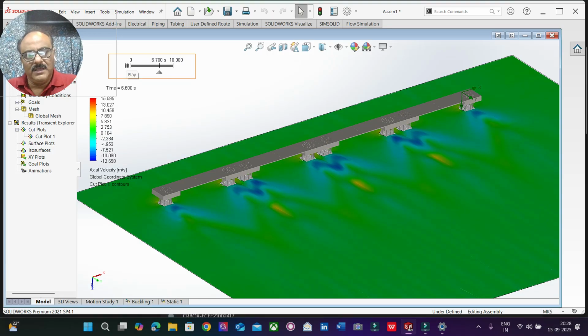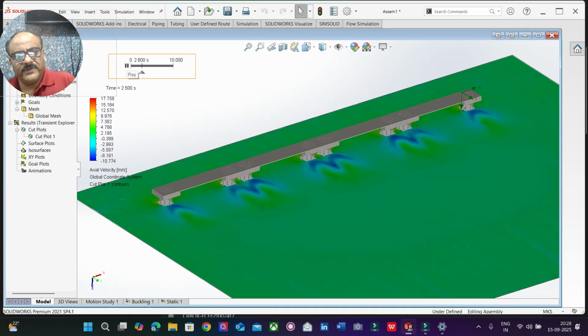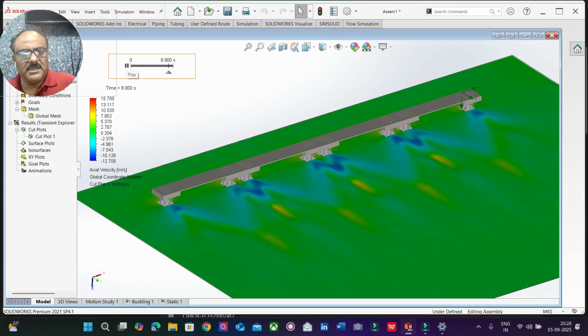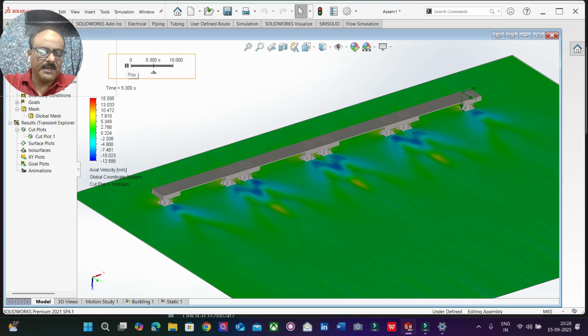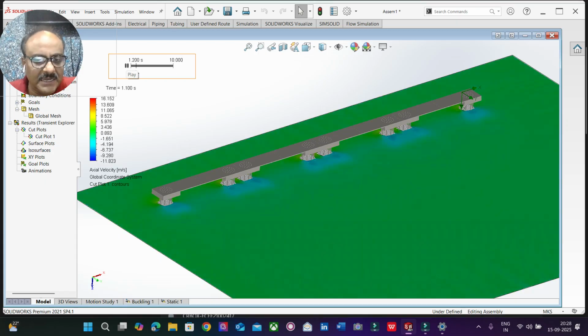So from that we design the structure for direct stress, the bending stress, and the combined stress. And we also calculate the shear stress. We find out the members, what should be the area of steel, what should be the area of concrete, and based on that we will integrate it across the height and find out what is going to be the volume. So this much cubic feet of concrete needed, and this much cubic feet of steel needed.